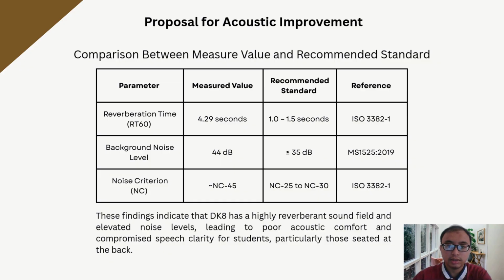And for the noise criterion NC, the measured value is NC 45 and the recommended standard is NC 25 to NC 30, and the reference is from ISO 3382-1.